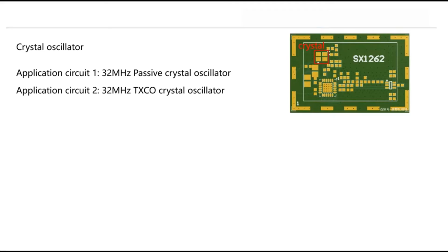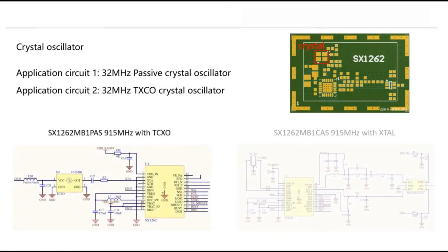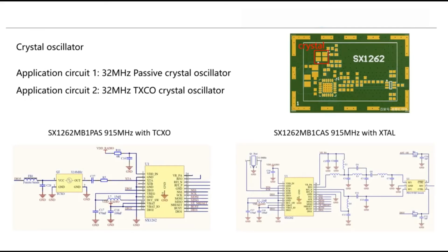For instance, if we download this reference design from the SEMTECH website, we can see on the left hand side they are using TCXO as a crystal, and then on the right hand side they are using the passive crystal oscillator.